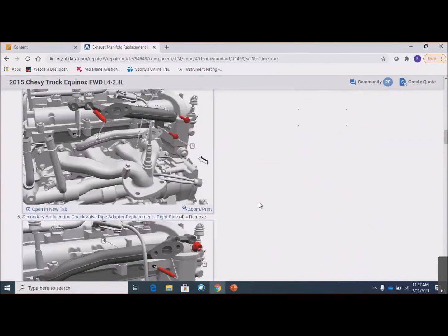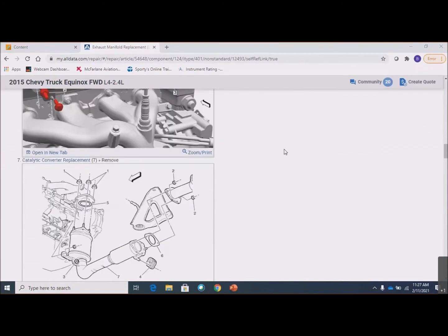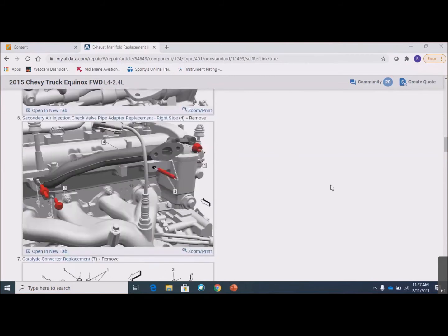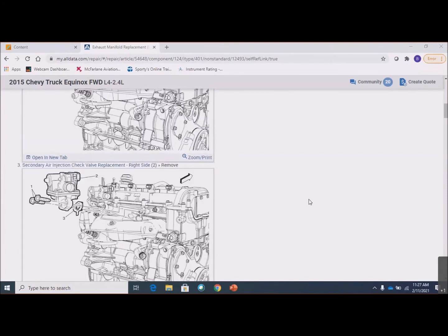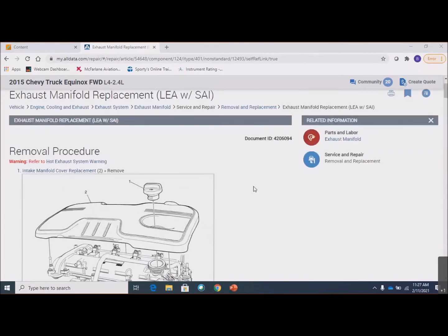So where these pipes here, right? The end of this pipe bolts on to where these little ports are here and there. And these 4 ports were absolutely and totally plugged solid. So kind of a pain, we had to drop the exhaust, we had to pull the exhaust manifold off and all that, but got them cleaned out, cleared the code, and the vehicle's back out on the road, and so far, so good. Put everything back together.